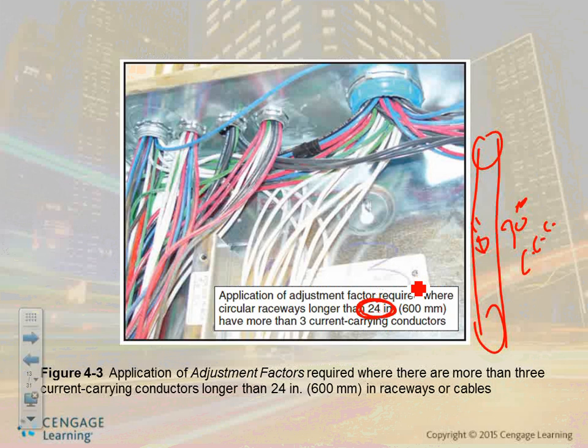Now you're talking about might as well just use surface mounted raceways, or a better wiring system, which would be cable tray. Cable tray, they don't have to have a cover, so they just open up in the air. The reason why we use conduits is for physical protection, and for physical protection, they have to be tight to protect them from the elements and what not. So it would be interesting to have a conduit. I'm not aware of a conduit that has holes in it. It would be a good wiring method because it will protect you. You just put little holes for the air.